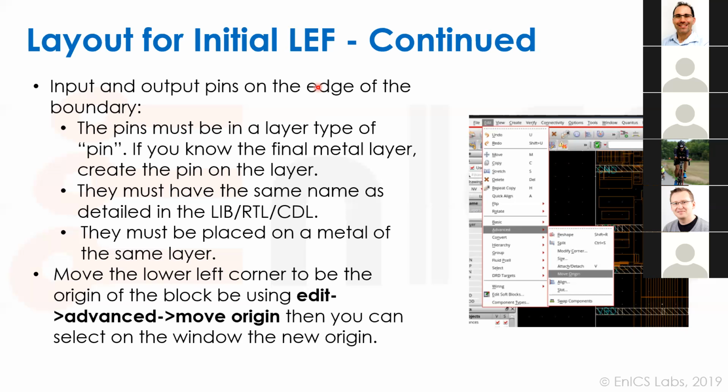I think it's sufficient that only the main power rails will be exposed. You don't. Yes. I mean the top level. Yes. Maybe top 2 or top 1. Yes, but not all of them. Yeah, that's what I meant. The top level should, so you can drop vias from the power grid that goes above it.